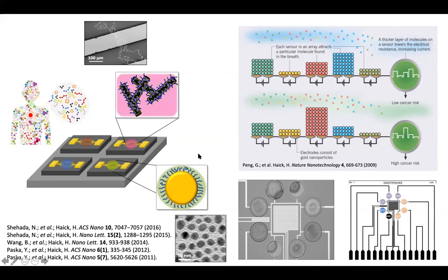And if you want to refresh the sensor, to take a second measurement, what do you do? Absolutely. Because we don't have a chemical reaction, refreshing the sensor can be done by applying a small, short vacuum. Sometimes we can use a few hundreds of milliliter, or you just blow it with fresh air or fresh nitrogen. Okay, great. Thanks. Thank you.